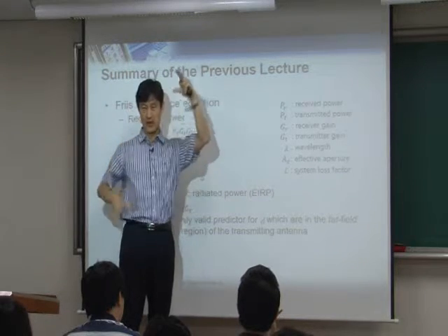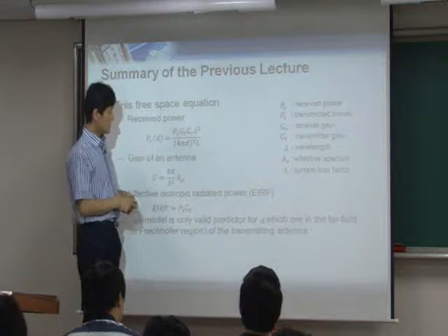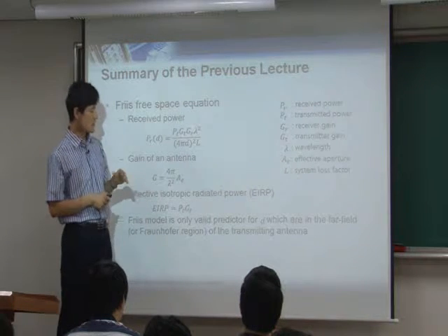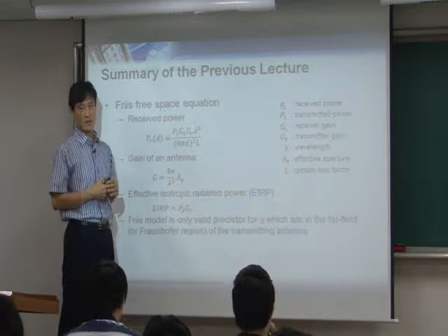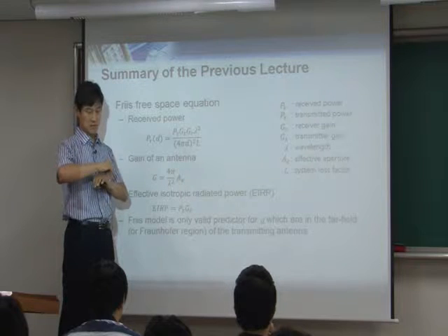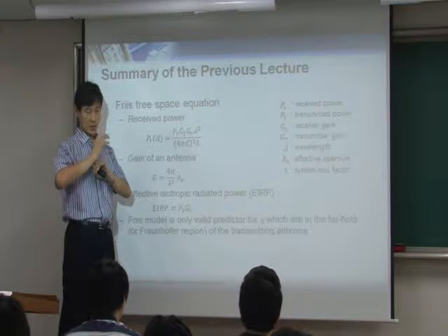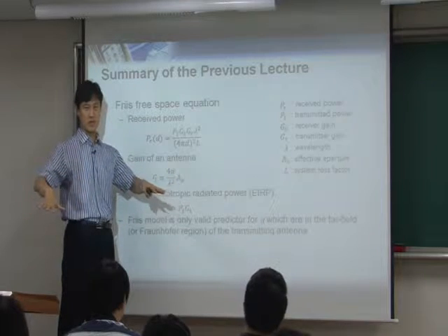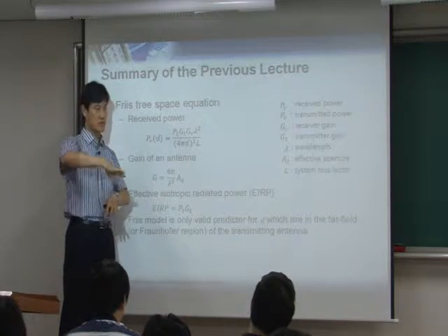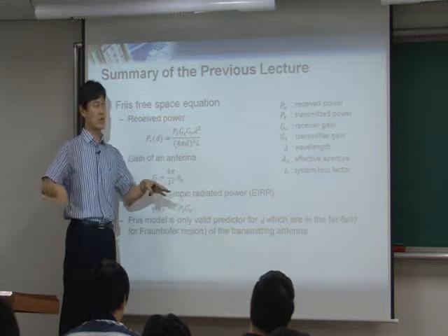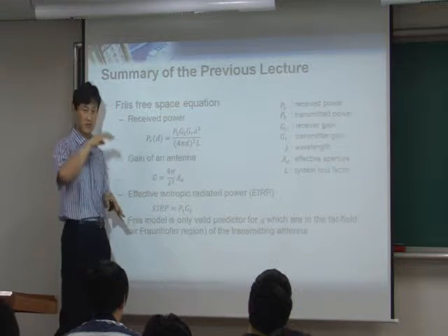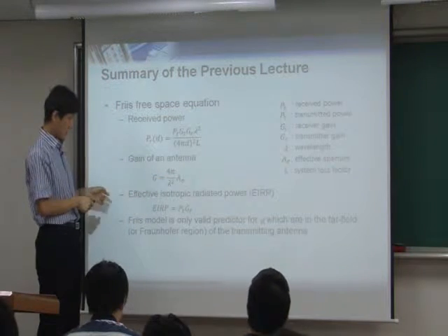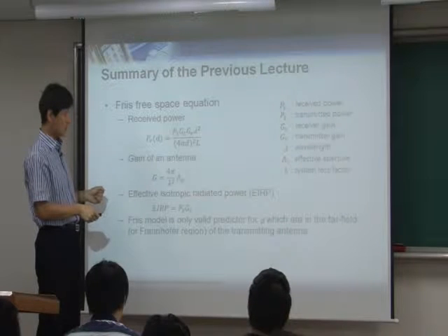It explodes everywhere. Whereas sometimes you see terms like omnidirectional. That basically means that your wave spreads over the horizontal plane. Omnidirectional means 360 degrees on the horizontal or azimuth plane. So anyway, here's the effective isotropic radiated power.